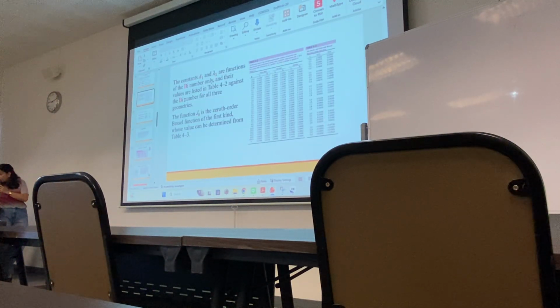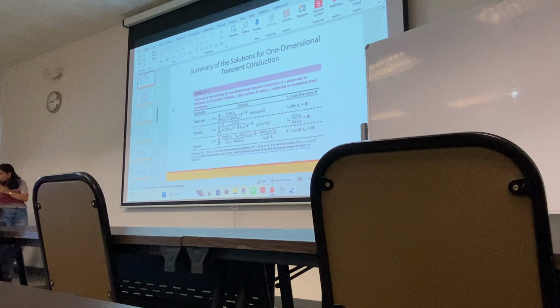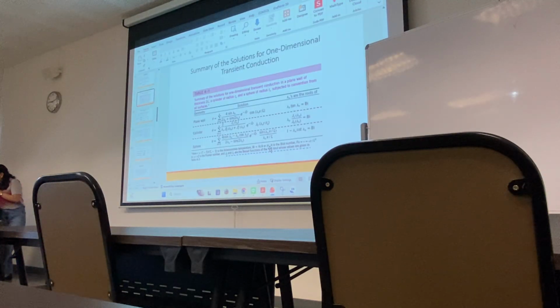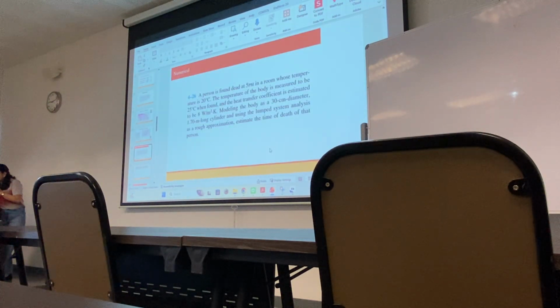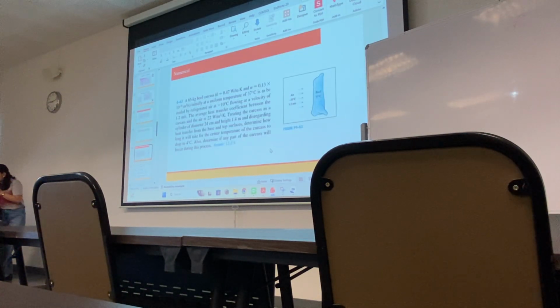So in this one you see your Biot number uses R. It changes to R, the radius, for a cylinder or a sphere. Okay, L is for a plane wall and R is for a cylinder and sphere. This is what you were asking? Right? Yeah, this can be confusing. So when you are checking, if it's a cylinder or a sphere, it becomes R.